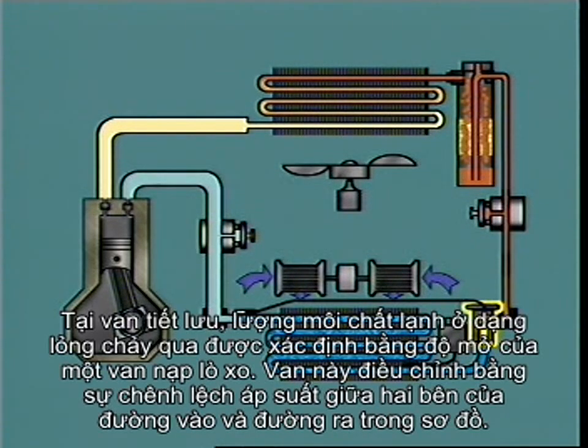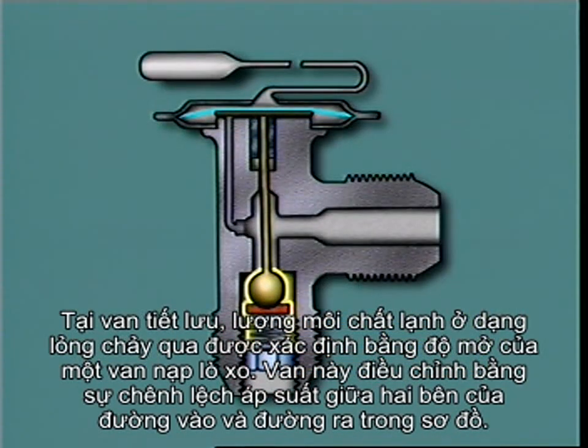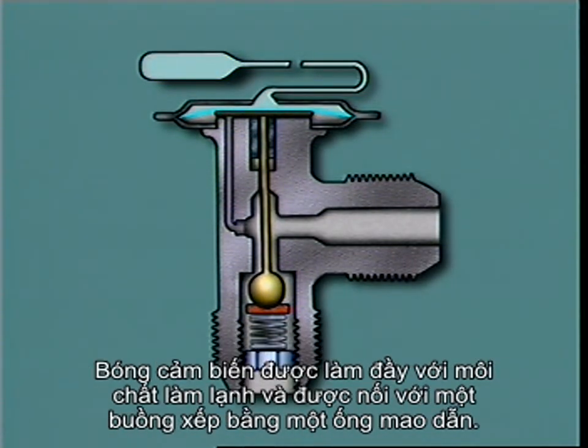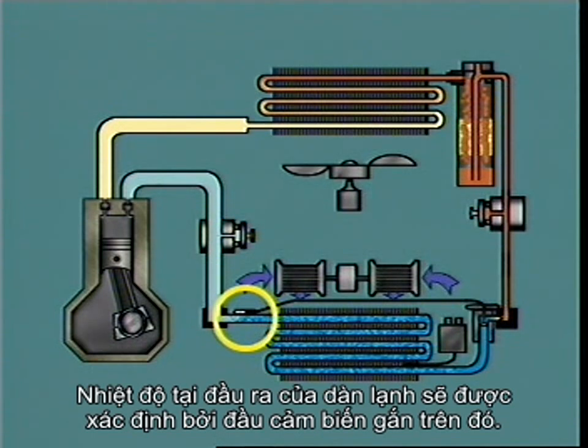At the TX valve, the amount of liquid refrigerant flow is determined by the action of a spring-loaded valve, which is controlled by different pressures on each side of a connecting diaphragm. The pressure in chamber A is determined by a temperature sensing bulb, which is taped to the evaporator outlet and insulated from air temperatures. The sensing bulb is filled with refrigerant and is connected to chamber A by a capillary tube. The temperature at the evaporator outlet determines the pressure in the bulb.